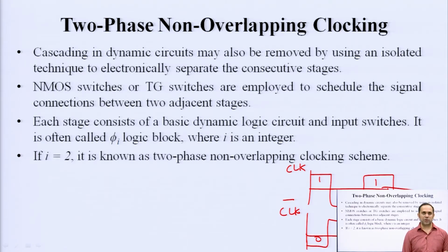Okay. So, both of them should not be high or logic 1 at any given point of time. Both can be 0, one can be 1, another can be 0, vice versa, but they both cannot be 1. So, if I pass these two signals through an AND gate, I should always get a 0 at the output. Okay. This is particularly useful in a transmission gate arrangement.